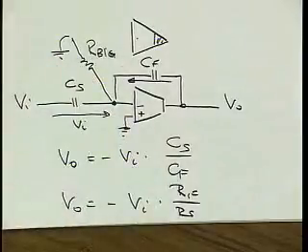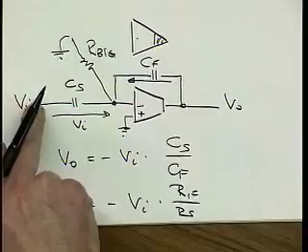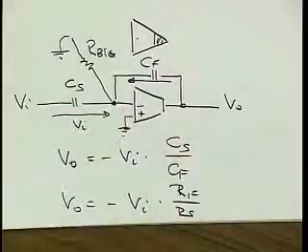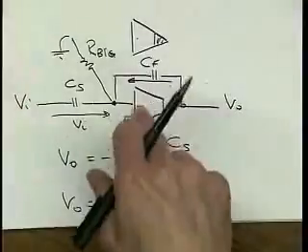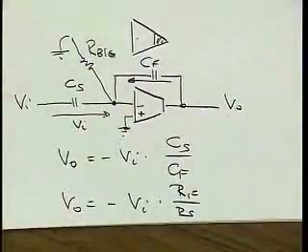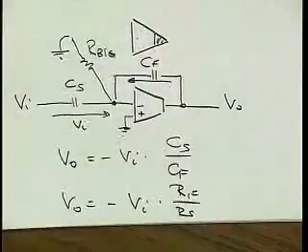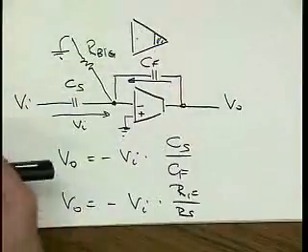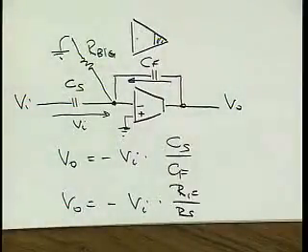And the other one is that the characteristic from here to the output would no longer be a constant gain that ultimately rolls off when this thing loses steam, but it would have a zero at low frequency, depending on how big we make this resistor. So it really would not be a DC amplifier anymore. It would be AC coupled. So that's another practical problem.